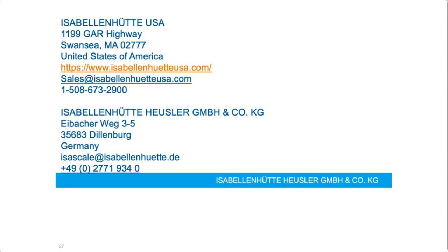Yes, good question here too. So this depends on the configuration possibilities of your isolation monitor, obviously. The module that we offer allows you to position the monitor either on the positive or a negative leg of the battery to get valid readings. So it is also capable to read current bidirectional. So you can either use it on the plus side or the minus side of the battery. However, for other isolation monitors out there, they might be configured for use in different locations. But with the system that we looked at, you have those two possibilities.